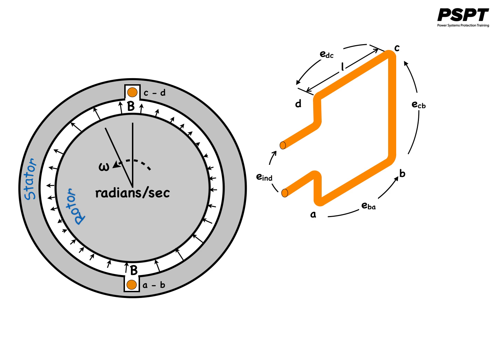Vector B is the flux density in the air gap between the rotor and the stator. It varies, as I said, sinusoidally with magnetic angle alpha of the rotor, while the direction of B is always radial to the rotor.